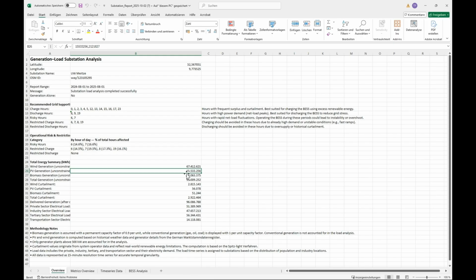Because as a rule of thumb, you can assume that if the redispatch or curtailment is lower than 2%, it's still good to build the same resources at a certain connection, whereas a curtailment of 5 to 10% or even higher is not really good for the resource to be built. So I wouldn't recommend here to request, for example, more wind capacity. In comparison, PV seems to be good, but we can also try to understand how much PV is good here.